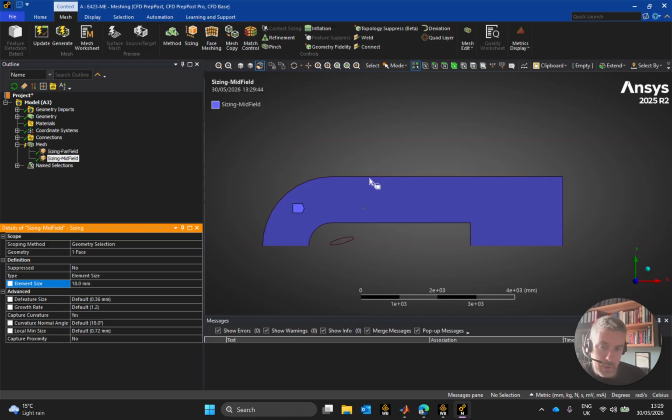So I'm not really that worried about massive jumps. I'd like to always keep it to 3 max, but 4 is fine out here where we're going with relatively coarse meshes. For the next one I'll maybe bring that down to 6, or I probably could get away with taking that down by 4 again. See how we go. Element size 18, the feature size, all looking okay.